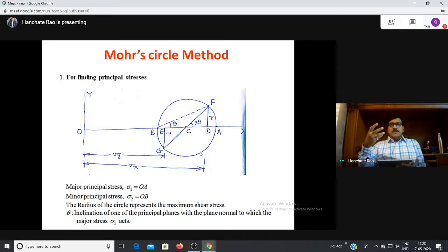What we are going to do is apply a huge amount of pre-stress even before the member is loaded with external loads. Even before the member is loaded externally, by using what are called steel tendons, we apply a huge amount of pre-stressing force on the concrete member. Before loading itself, we are applying stress. So that is called pre-stress.